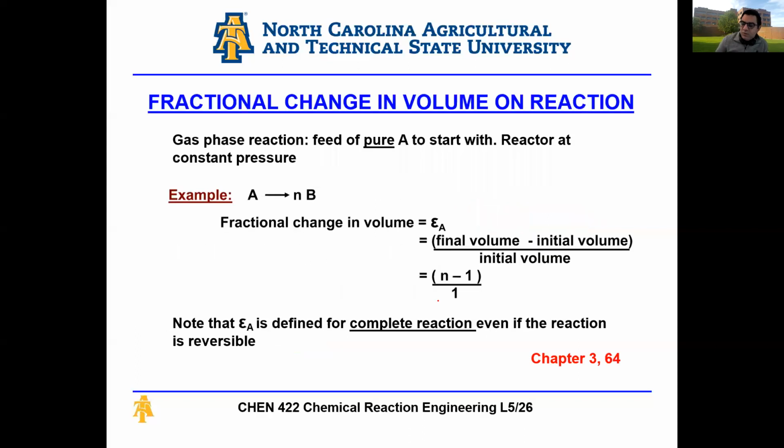Then one last point for this lecture, we're going to talk about fractional change in volume of reaction. And this is something important to recognize because, especially for gas phase reactions, if you have a change in pressure or a change in temperature, whatever it is, your volume is going to change, right? Unlike a liquid where it's incompressible, there's no change in volume. So for a gas phase reaction, a feed of pure A to start with, and your reactor is at constant pressure. So let's look at this example.